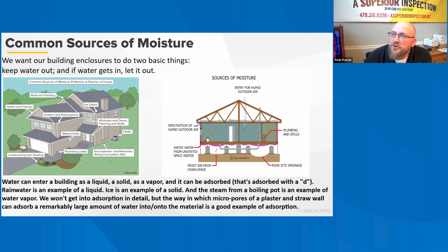This concept of moisture movement can be complicated to understand. One issue is that we have and use so many different terms, including air barriers, vapor diffusion retarders, vapor permeable and impermeable. Home inspectors often find it challenging to speak with contractors and building officials without using the same terminology. The most important terms a home inspector should understand are that a vapor retarder retards the movement of water by vapor diffusion, and a vapor barrier is a vapor retarder of a certain class, such as a class 1 vapor retarder.